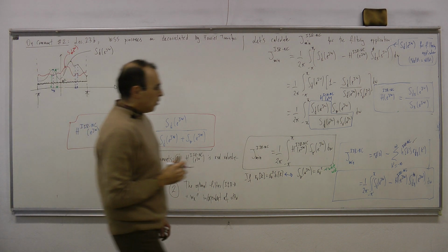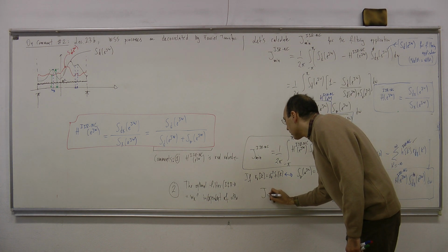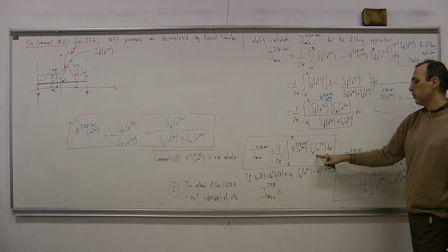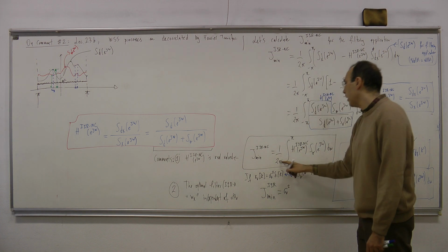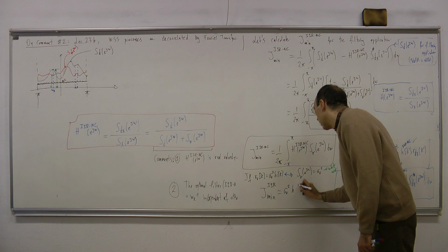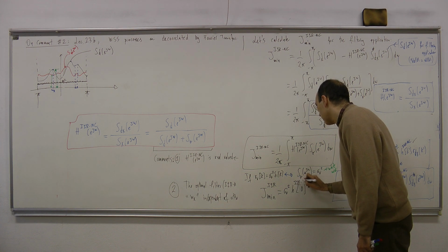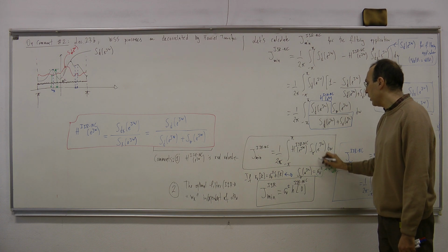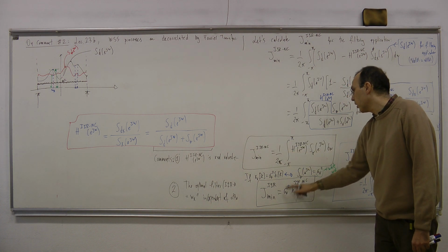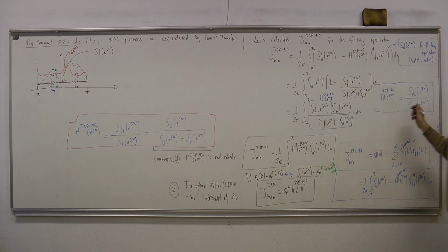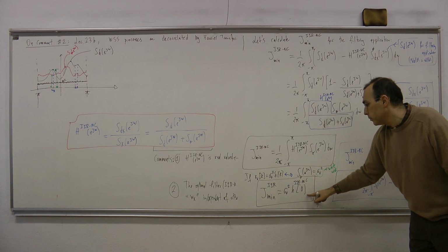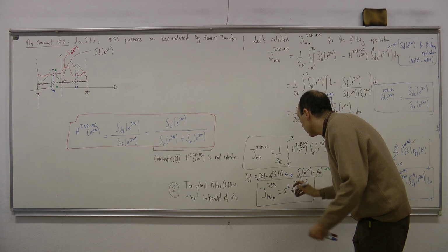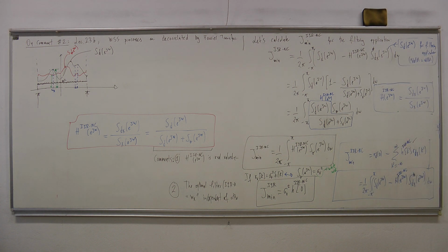Okay, so if this is the case, then J min IIR, just insert this value over here. I have sigma v square times, well, I get a very simple result. The reason is, if you include this thing in this integrand, then move it out of this integrand. What remains is the area under the frequency response of H(e^j omega), which corresponds to the zeroth sample of this impulse response. So for white noise, we get an especially simple result, sigma v square h0.